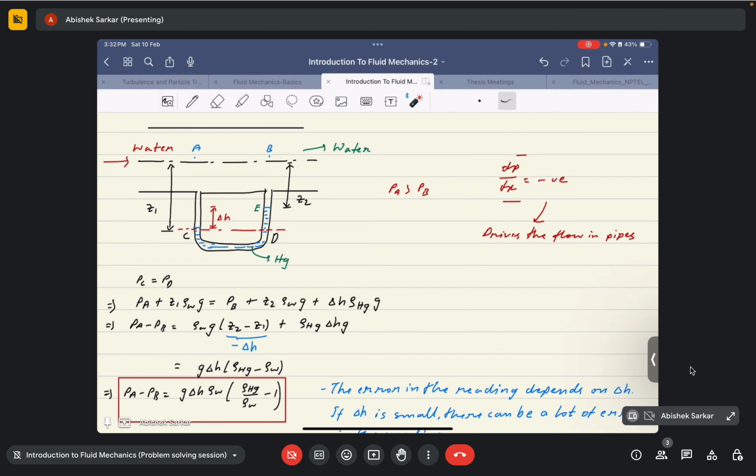So let's assume that point A and point B are at this center line. The distance between point A and the upper surface of the mercury in the left arm is Z1. In the case of point B, the distance between point B and the upper surface of the mercury in the right arm is Z2.